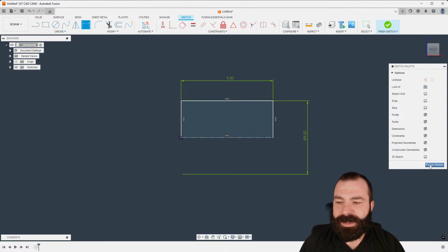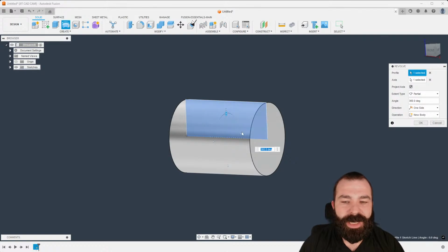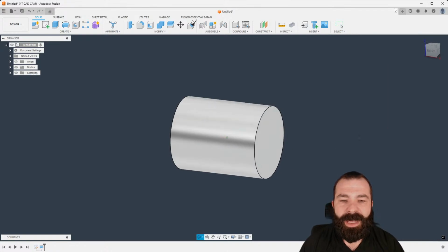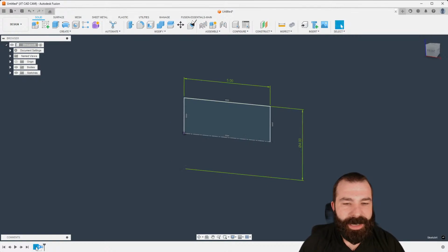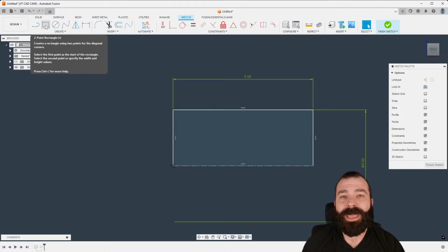Just to give you an idea of the shape and profile of what we have going on, as you can see, that is going to be our stock that we're going to later use in setups. So let's go back to that sketch and add some more detail. A few things you may now need: let's say, for example, this is going to be held in a collet system on the main, and then we're possibly going to do some soft jaws or a 3-jaw on the sub.